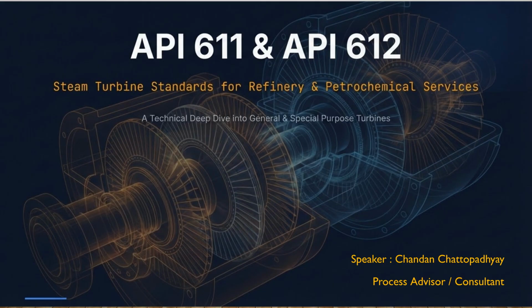I am Chandan Chattopadhyay, process advisor, and today we are exploring the critical differences between API 611 and API 612 and the invisible forces governing steam turbines in refinery and petrochemical services. Why does one cost five times more than the other? Why does one need a solid forged rotor while the other gets away with discs shrunk onto a shaft? All the answers are coming up now, so let us dive in.